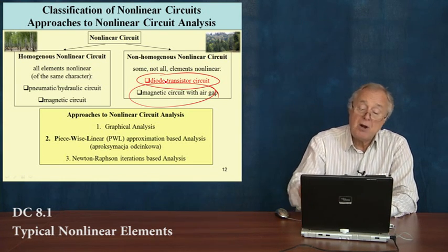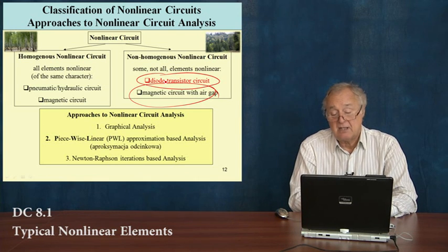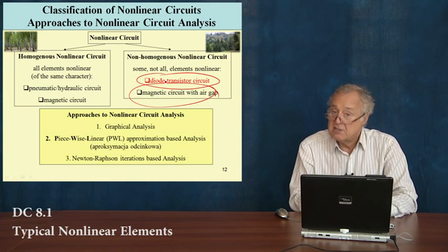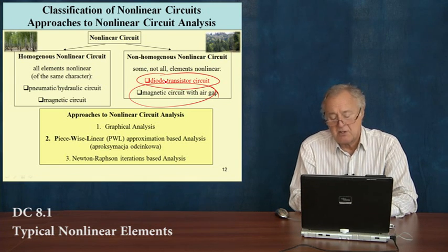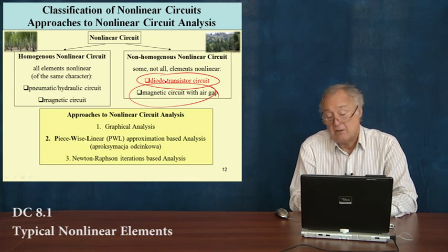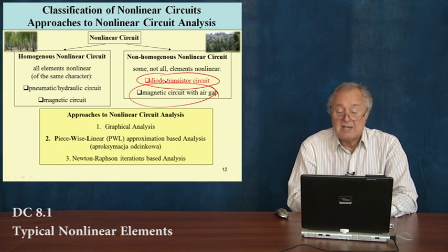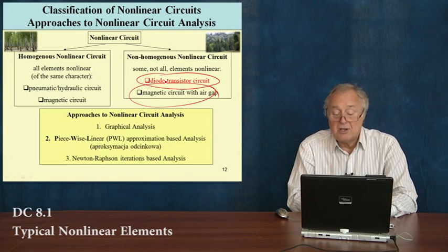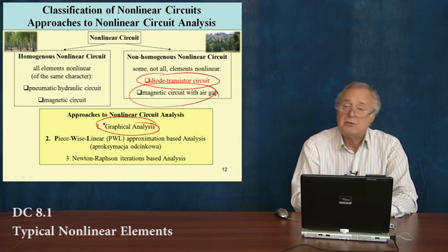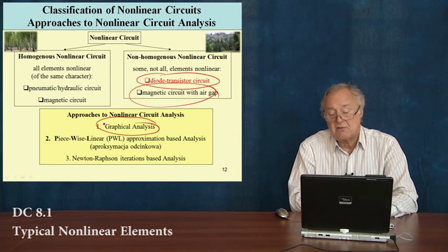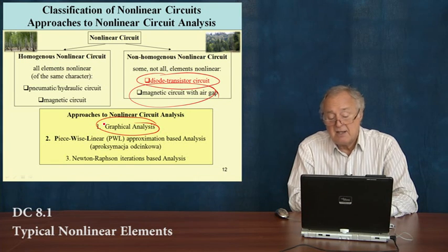Then approaches to nonlinear circuit analysis. A nonlinear circuit is described by a system of nonlinear equations based on Kirchhoff's laws, and there is no Ohm's law. There is an IU relationship describing the nonlinear element or elements. The first approach, which is applicable to a simple circuit, is graphical analysis.